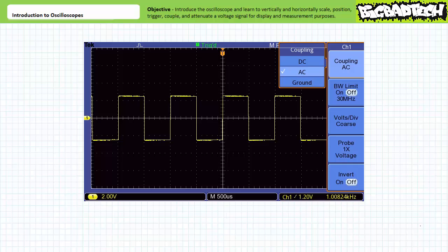Note, AC coupling is a principal source of trouble for individuals viewing DC waveforms. If AC coupling removes all the DC, when displaying an entirely DC waveform, flatline output is to be entirely expected. DC coupling shows the waveform in its unadulterated form with both DC and AC components. AC coupling drops the DC and can sometimes give a user a false impression if they aren't aware of this modification.